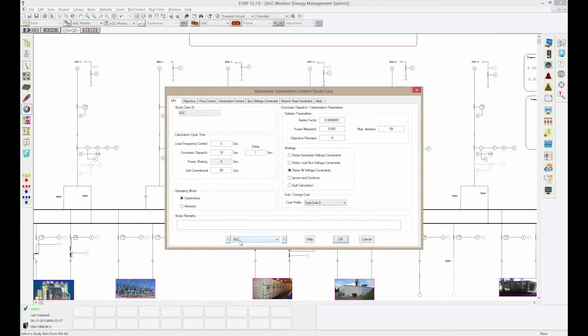That means if you have a different control strategy in summer versus winter, or during day versus night, or under various unique operating conditions of the system, these can be pre-created by the engineer and made available to the operator with an easy to recognize name, so that the operator can easily switch between the control strategies without having to reconfigure the system.